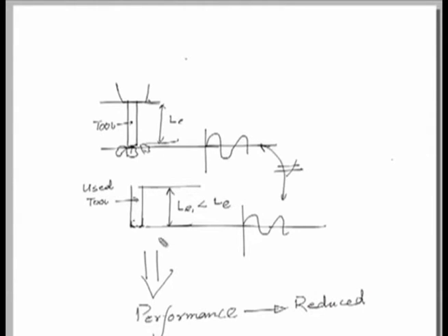Thus, it is very important that the tool length or the tool dimension remains the same while working with USM. The vibration amplitude varies at different locations along the tool axis, as we have just discussed. If the length reduces, then the vibration amplitude will no longer be similar, and consequently we will not get similar performance from the same tool. Although it is the same material and the same tool, because of the change in effective length the characteristics will be different, and tool wear changes the location of the tool tip, causing inconsistency in machining.